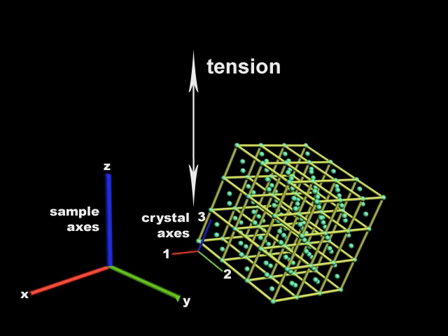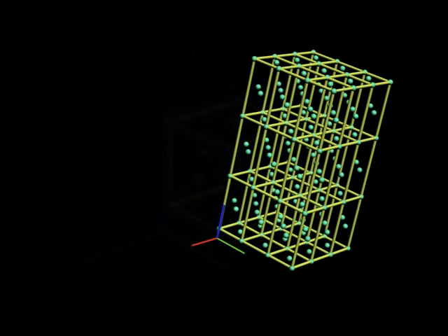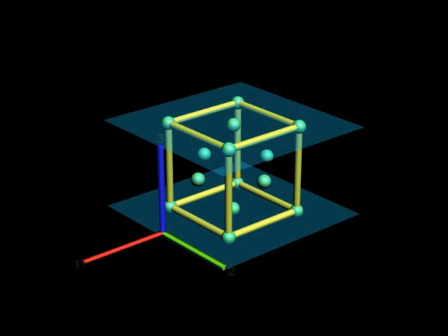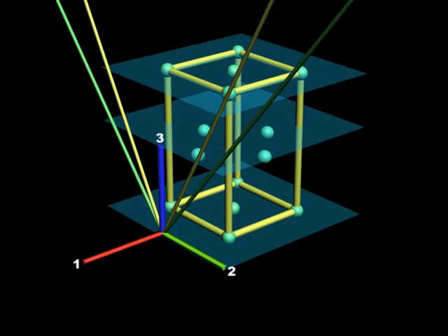As part of the slip process, the lattice rotates. It also distorts elastically, as shown here in a highly exaggerated manner. The distortion of the lattice can be detected experimentally by using diffraction methods. A displacement of one plane relative to another in a constant wavelength radiation diffraction experiment causes a change in the angle between the inbound and outbound beam, as given by the Bragg condition.